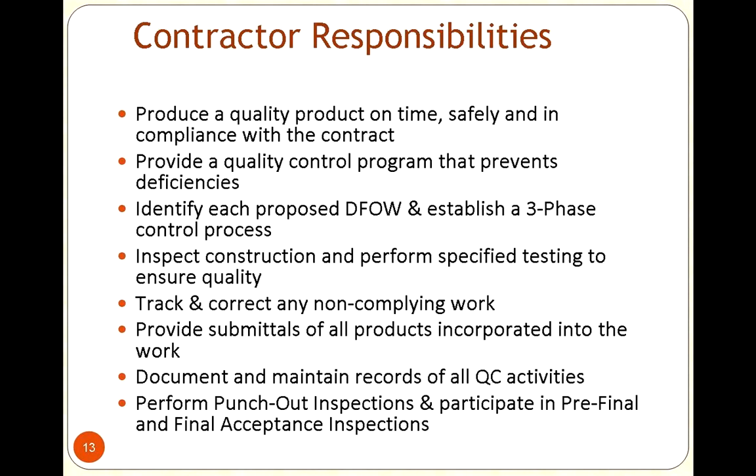Now, there were always things that would be a little fuzzy in the definition. And that's one thing I always tell people: don't have any fuzziness in the contract, the scope of work, what's defined, what's expected. Never use the back of the napkin approach. Never use just a conversation. Define it, list it, and be specific as needed, especially when it comes to documentation, drawings. I'll talk a little bit about that when we start going into submittals.